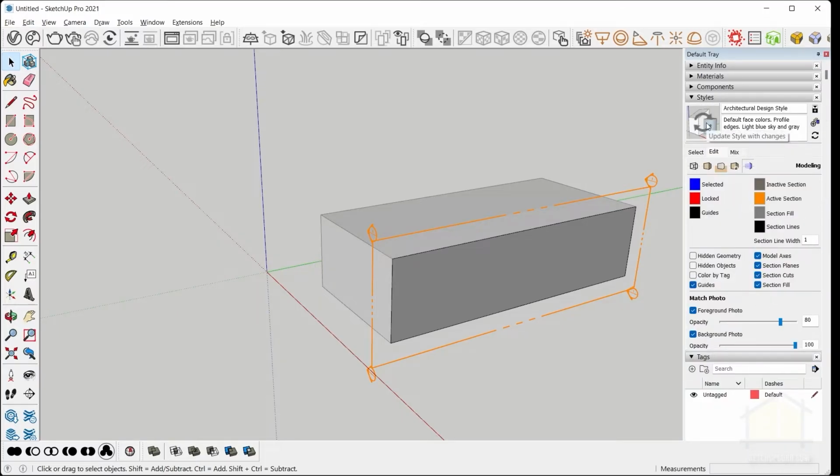And also you can notice that this circle has come on the styles icon. So I'll need to click on this, and that would update the style as well. So you can either update the style, or you can also create this as a separate style. So you can click on create new style, and then you can rename this to drafting for layout style. So this would be saved here, and then click on the circle button to update the style.